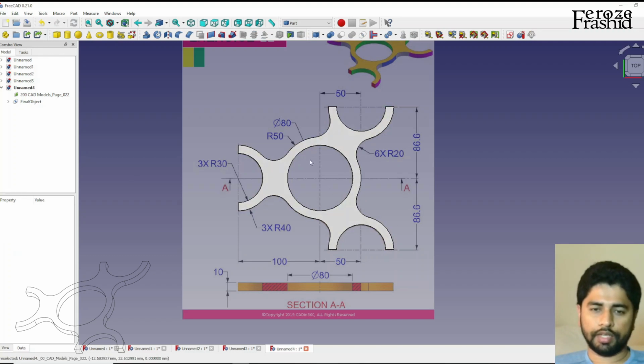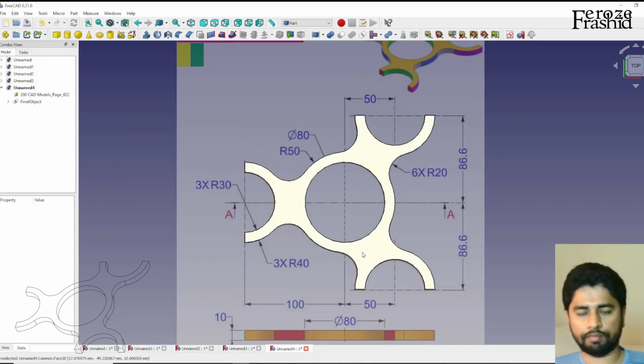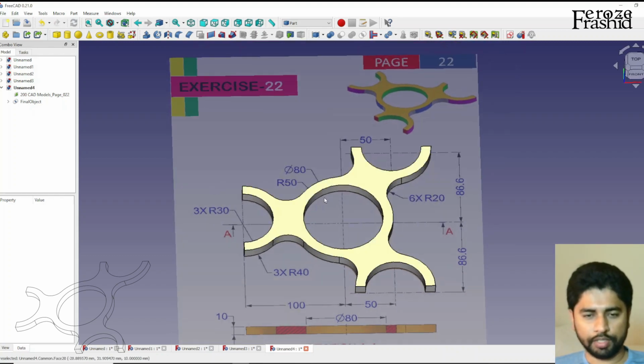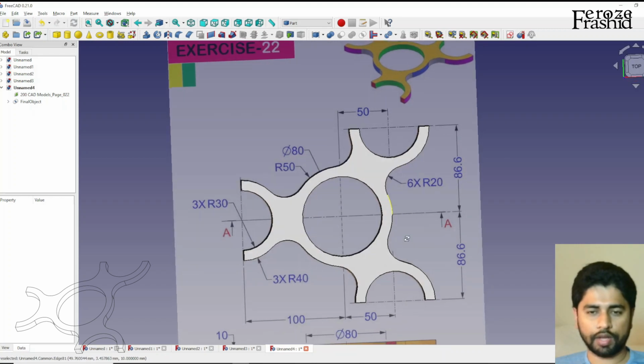Okay, so what I did, this was definitely a bit more tricky for only sketching. What I did was I built this part and then replicated that 2 more times, and then I built a boundary rectangle and kept the intersection only. That way I did not have to sketch the entire part individually.